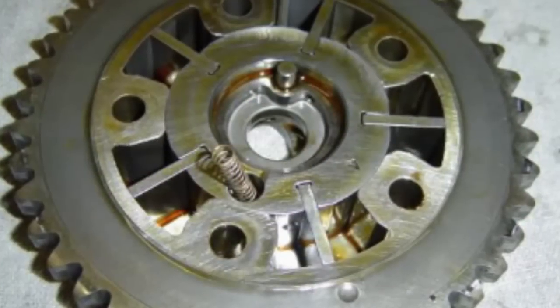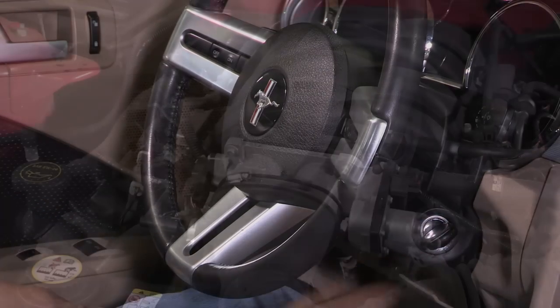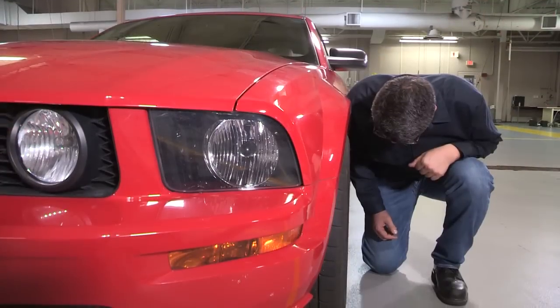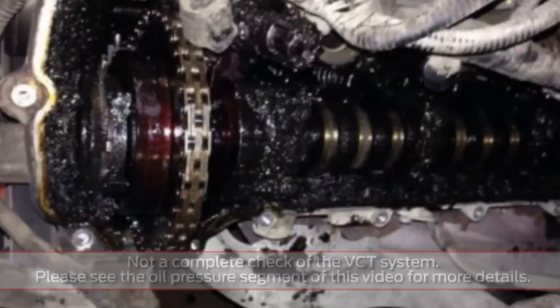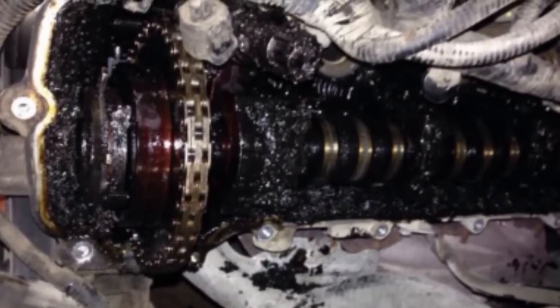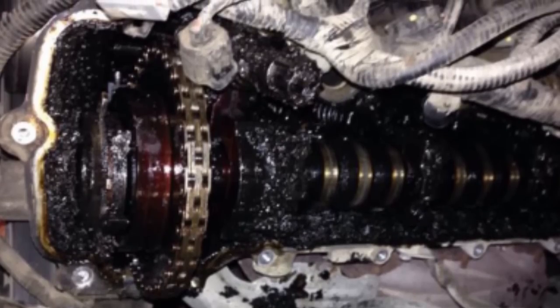Another important area to check for signs of mechanical failure is the VCT phaser itself. If the phaser is internally compromised, it can cause issues with cold start drivability, idle quality, engine noise, and while driving. Don't forget to check for signs of a lack of maintenance, such as sludge or metallic debris that could impact the VCT phaser's performance under a variety of driving conditions.